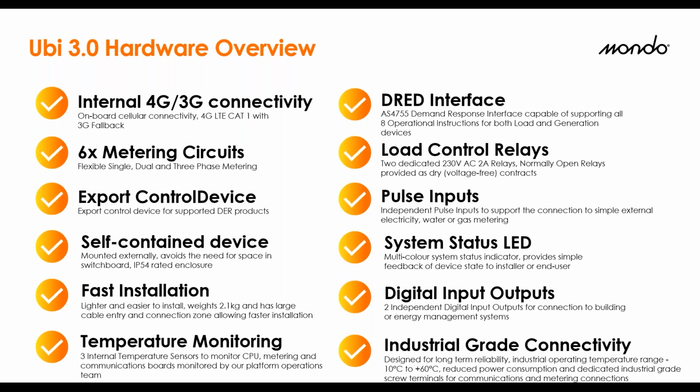So as I said, 6 metering circuits. It's got the 4G, 3G fallback on there. You can put in pulse inputs. It's got DRED capability. Also, you can do temperature monitoring if you want to do temperature sensing. Also, it's pretty much all contained in the one device, IP54 as well.